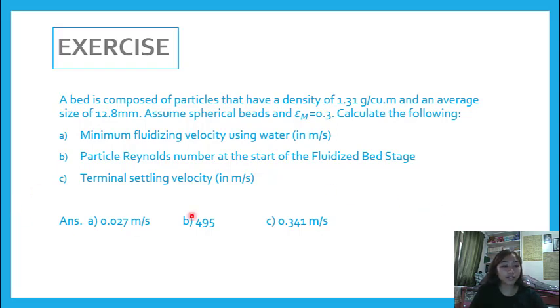And I have here the answers. So, for computing the minimum fluidizing velocity, we can use the Ergun equation in its quadratic form.